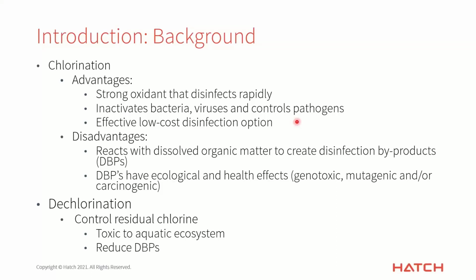Just a bit of background now on chlorination and dechlorination in general. Basically, some advantages of chlorination are that chlorine is a strong oxidant and it can disinfect very rapidly. It inactivates bacteria and viruses and it can control pathogens. And compared to other disinfection options, it can be quite low cost, but still very effective. But a major disadvantage is that it reacts with dissolved organic matter to create disinfection byproducts, also known as DBPs. These can have ecological and health effects that can be genotoxic or carcinogenic or mutagenic and just not very good for human health.